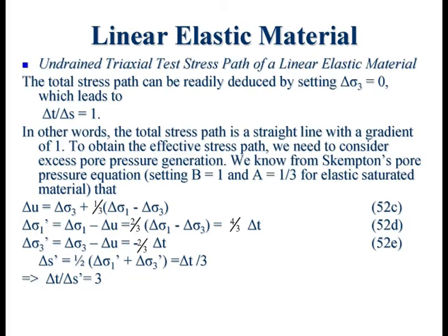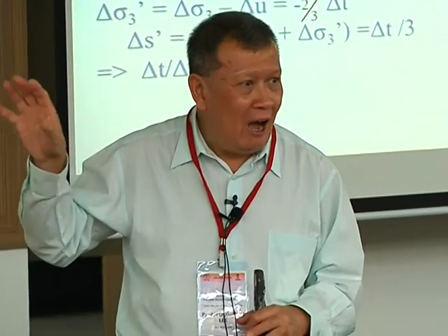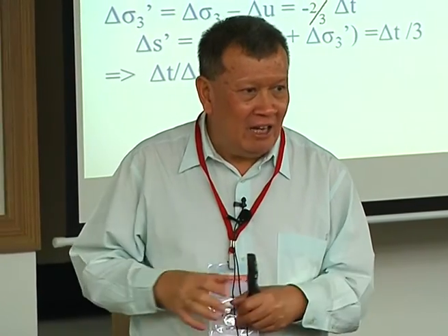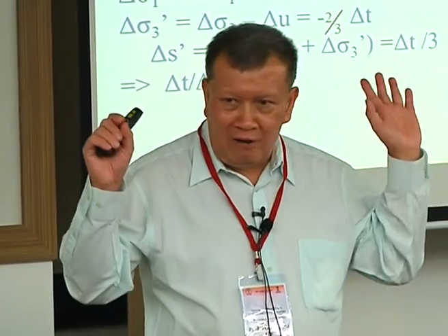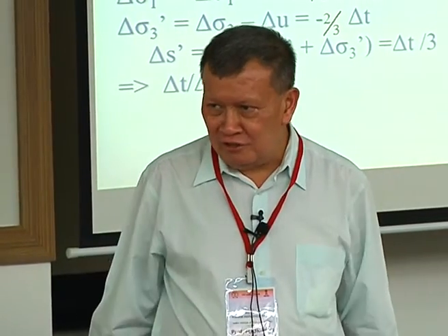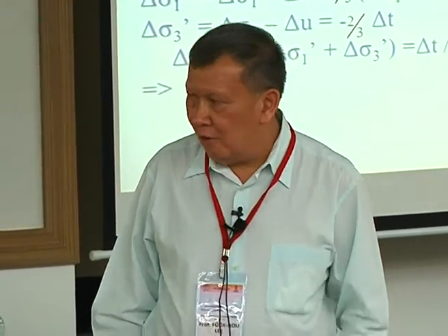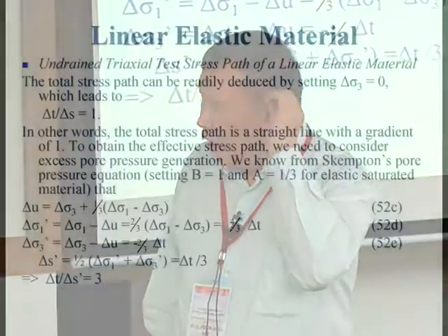So the general approach, the usual approach to deducing a stress path, I would say works 95% of the time, if not 99% of the time, is to just consider the change in the two parameters and at what rate they are related to each other. That's all you need to do. You don't have to go integrating and do all kinds of funny things. Just consider the change. Is that all right? Okay. So that is the simple way of doing it.